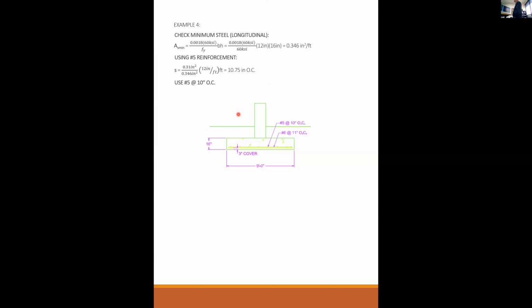Well, no, the footing becomes heavier, so you have to recheck your allowable soil pressure. And if you were really close, you might have to make it wider. But when you make the footing deeper, it's not because you make it heavier that it resists the shear, it's that you have a deeper D, and the shear is a function of the width times the depth.